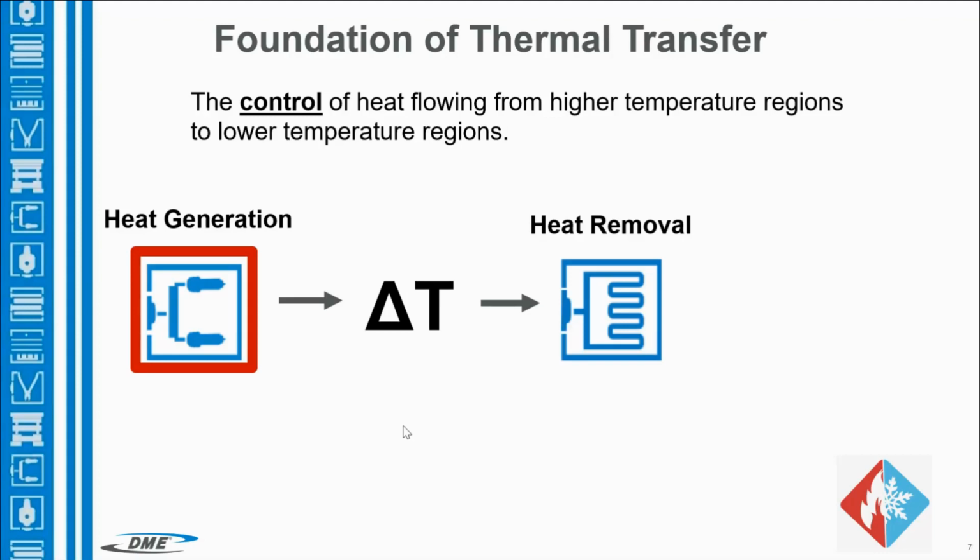And the difference, or the delta T, the difference in temperature between the heat input and the heat that we want to get out of the plastic so we can eject it. And in that heat removal, it's really dependent on what type of resin that you're using, because it's only going to give the heat up so fast. And then the tool steel that you chose to use, the water temperature or oil or whatever cooling media that you're using. But you also have the ambient temperature around your molding environment.